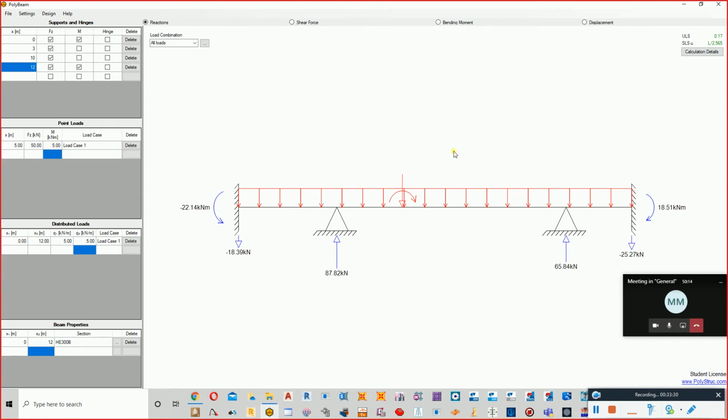Okay. If I want the shear force, I can go and click from here. So this is my shear force. Okay. So going down, because of the negative reaction, you can see the negative reaction here. The negative reaction means that these two reactions, because of the point load and depending on the moment which is occurring here, are too huge. So these are more than the load applied. So in this case, what we need to do is provide an opposite direction reaction. Okay, so this is the shear force.